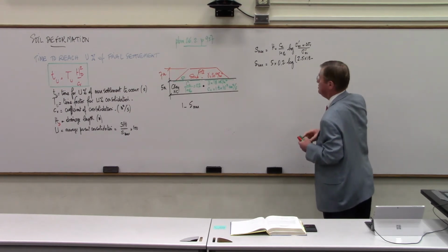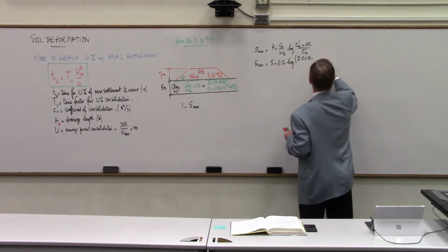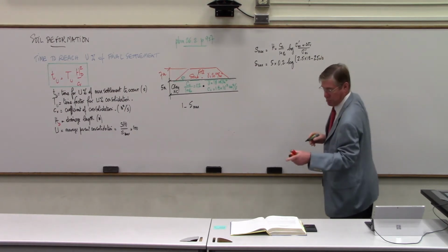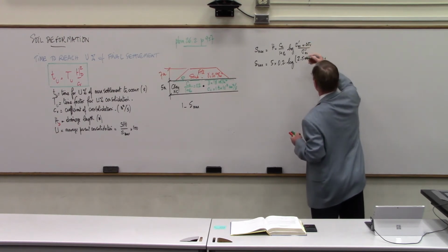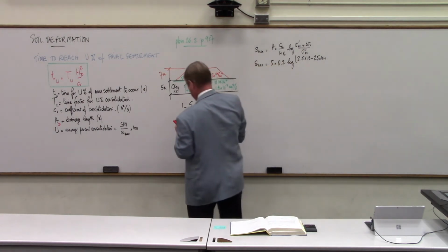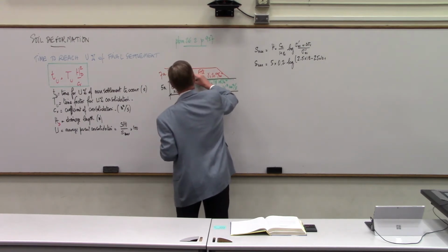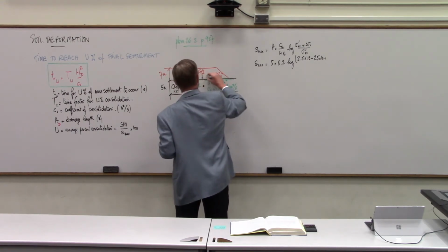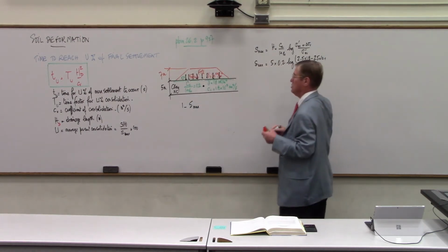2.5 times 18 minus 2.5 times 10 because of the water pressure. And I'll take 10 instead of 9.8. I think in the book I took 9.81, but so that's sigma prime OV. Delta sigma V. So there is a lot of load applied by the embankment onto the soil. How much is that load?